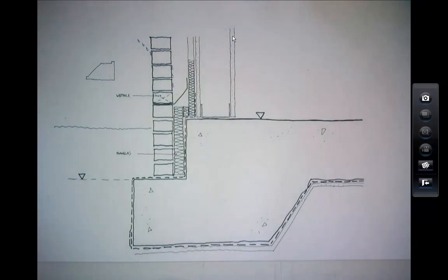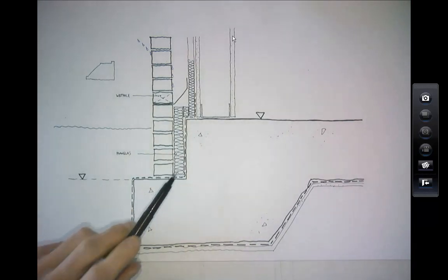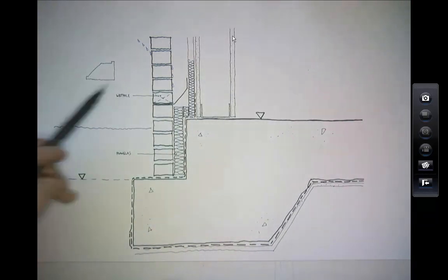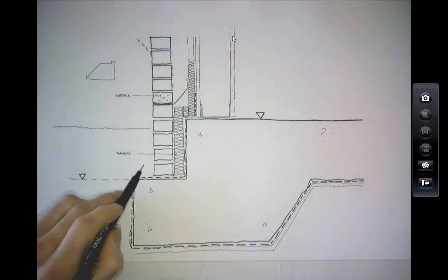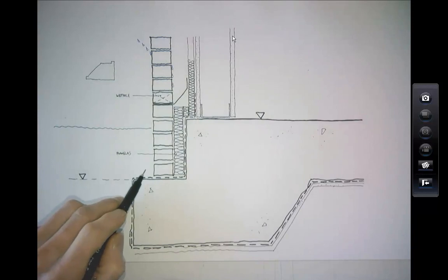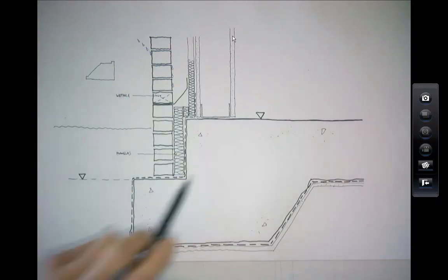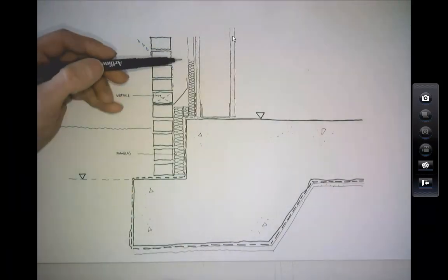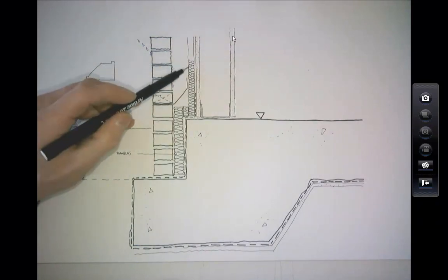Yeah. How much of that insulation do you need compared to standard? Well, it's complex because you're below ground. You've got a lot of soil, so you probably don't actually need very much at all. But you normally just put enough to fill the cavity. Okay. Now, cavity width, you'd be looking for at least 100 millimeter cavity to let you get say 50 mil of insulation in and the 50 mil air gap.